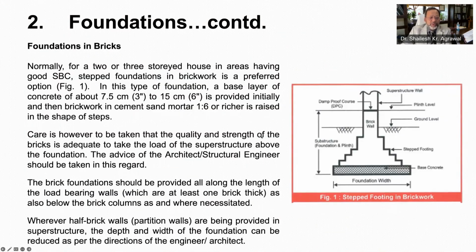Now let us tell you about different types of foundation. First is the most common one, that is foundation in bricks, which is shown here on right hand side. Normally, as thumb rules are adopted for construction of 2 to 3 story houses having good safe bearing capacity, step foundation in brickwork are universally adopted.